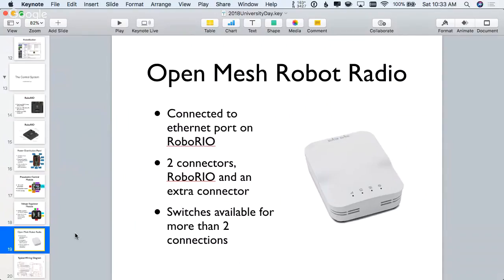There's PoE capability now as well. Power over Ethernet. Obviously the rules for 2018 have not come out yet, but in 2017 you were allowed to use passive injectors for the OpenMesh radio, and all that means is you would take apart an Ethernet cable, find the wires that let you apply power to the radio, and apply power that way.